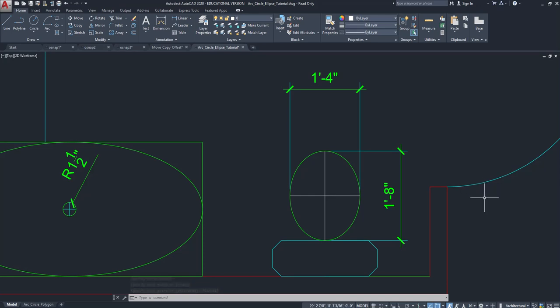One thing that you may not have noticed me doing, but that I indeed did do: did you notice that I created a line, I hit escape, and then without typing a command or hitting an icon, I reinitiated it? Did you see me do that? L for line, enter. I drew one. There's one axis. I hit escape, and then I reinitiated the command, snapped and drew it, escape, escape, without hitting L for line or the icon.